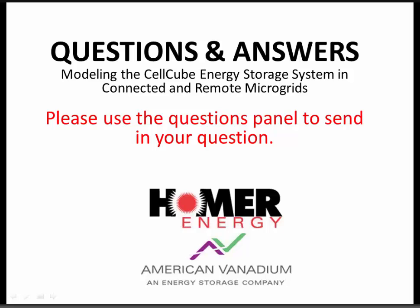So you've now taken up 10 hours, and you'd certainly get 2 full cycles per day. On the other side of that coin, we have had vanadium redox batteries working in conjunction with wind farms where they sit at 50% state of charge and then go through hundreds of minor discharges per day, absorbing and discharging, filling in the blanks on a wind farm. So it can do the full deep cycle, or it can just sit there and work as an energy buffer.